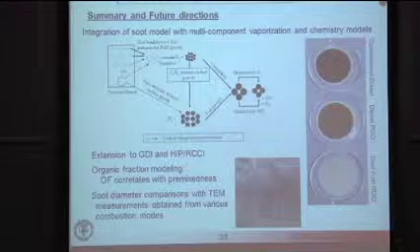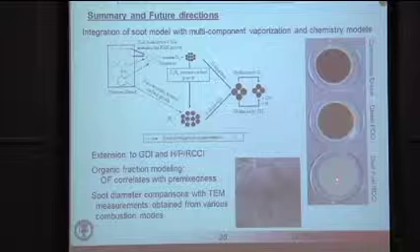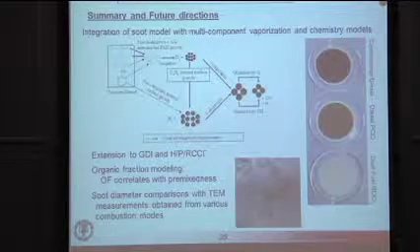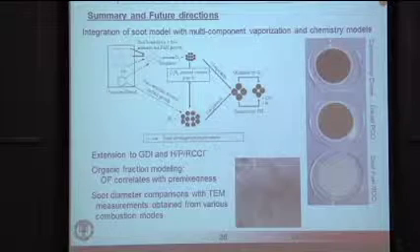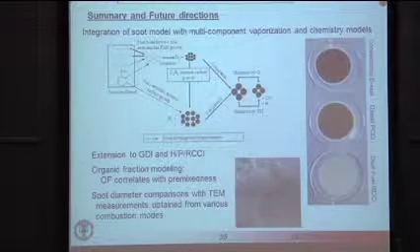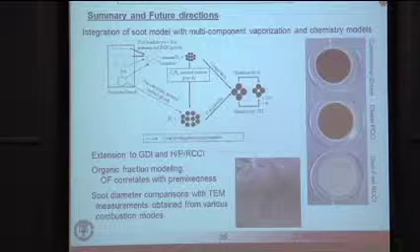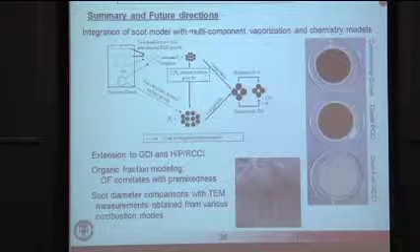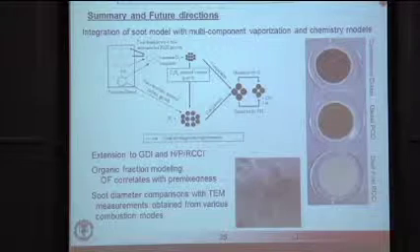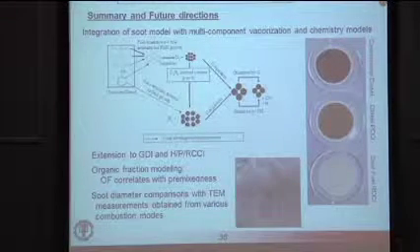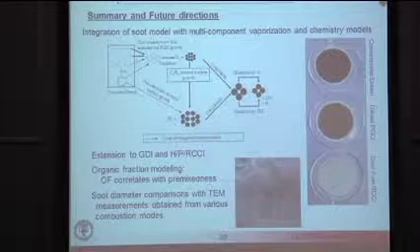You have to call it particulate matter because it's basically 99% fuel that is condensed onto very few elemental carbon particles. If you look at the TEMs here, most of this is high molecular weight hydrocarbons. It's not really carbon anymore. So we have to rethink our soot models to be able to predict that. And that's something that's currently in progress.